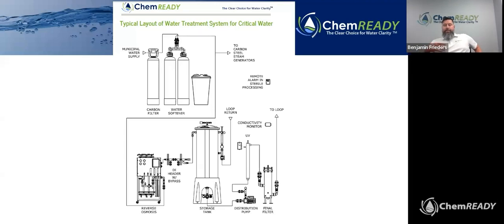All of that will feed to, now a requirement, a recirculation loop that would feed your washer disinfectors, steam sterilizers, and any other equipment that requires your critical water. Once those are fed to those devices, you would then have a return loop that comes back to the storage tank and then continuously recirculate that into a loop. So right off the bat, if you know you don't have most of these pieces of equipment, you can be pretty sure that you're not in compliance, and you're probably going to need to look into some capital expenditure for this.